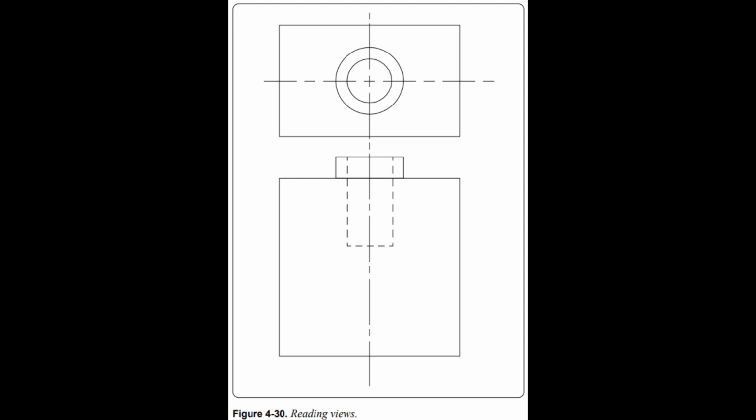After determining the shape of an object, determine its size. Information on dimensions and tolerances is given so that certain design requirements may be met. Dimensions are indicated by figures either with or without the inch mark. If no inch mark is used, the dimension is in inches. It is customary to give part dimensions and an overall dimension that gives the greatest length of the part. If the overall dimension is missing, it can be determined by adding the separate part dimensions.